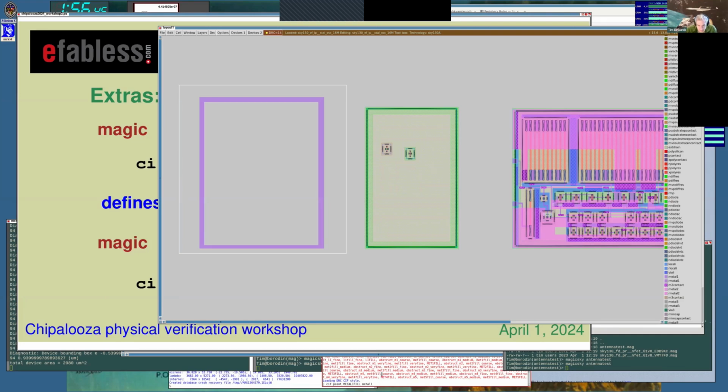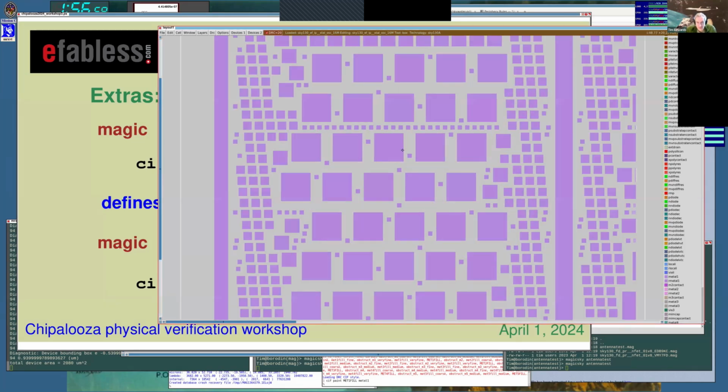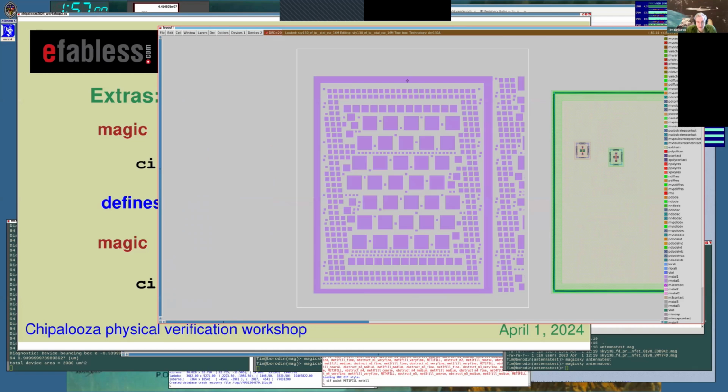And it didn't like that because it is not metal 1 fill. I have written that wrong on the page. It is met 1 fill. And I drew a little bit outside the boundary there, but you can see that is the fill pattern, and it's been represented here in metal 1 blocks. And so if you want to pre-fill your layout just to see how that extracts and affects your performance, then that's how you would do it.